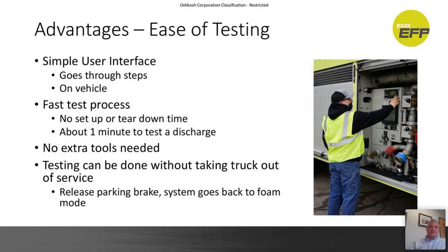And the testing can be done without taking the vehicle out of service. So if you take the truck out and you start a foam test and the alarm goes off, as soon as you release the parking brake on the vehicle, the truck will actually kick out of the foam test system and revert back into normal operations. So there's really no need to take a truck out, hook any systems up to it, and keep it out of frontline service if you're doing a quick test.